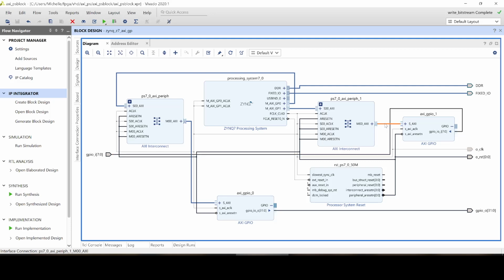That GPIO is going to this peripheral, and that peripheral is going to the other master. And that's how we're going to communicate within the master. And of course, as usual, anytime you have a clock and a reset, the block design creates a system reset controller.